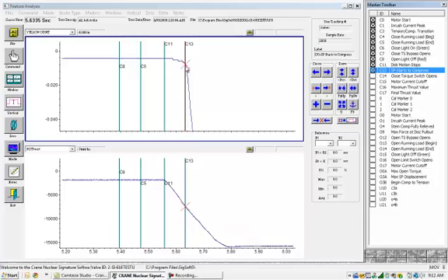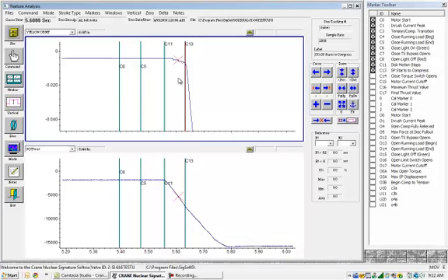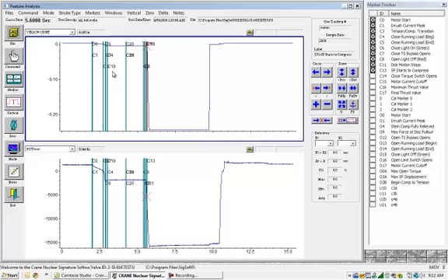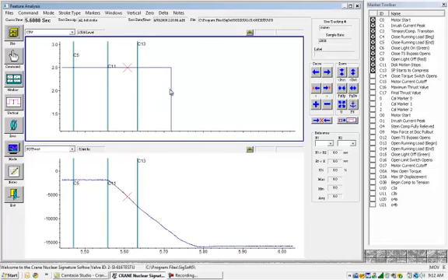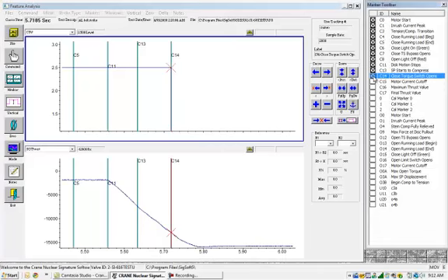Okay, our next one is C14. To bring up our closed switches again. C14 is our closed torque switch opening right here. Okay, motor cutoff and maximum thrust.